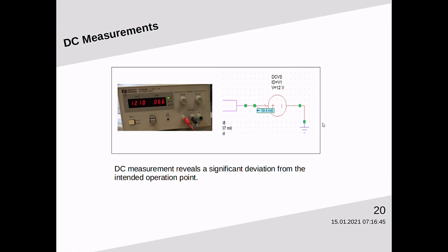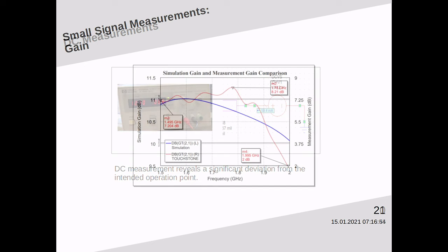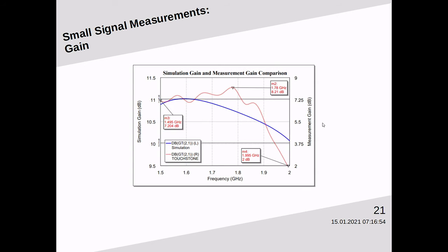There is nearly a 10% difference between the large signal model's predictions and the measurement. After elaborate checking of the lumped resistor values using a multimeter, I concluded that this is a device-level deviation from the manufacturing specs. Next comes the small signal measurements. I promised 10 dB gain, yet measurements show much less. On the other hand, up until 1.8 GHz, gain is flat as desired.